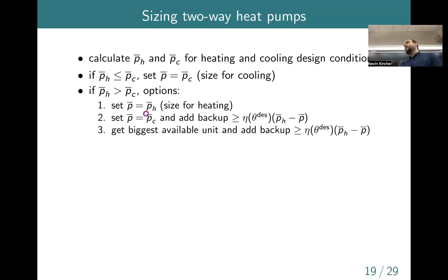There's also a humidification issue, which is that if you are short cycling, you only run for a couple of minutes, and then maybe you don't absorb much moisture from the indoor air. The coil maybe doesn't get as cold as you would like it to, so you don't get as much water condensing out, and so then humidity can rise. There are also other more technical reasons based on how fans are controlled, but basically humidity performance can get worse if you have very oversized machinery. Okay, anyway, so that's why you might not want to do number one.